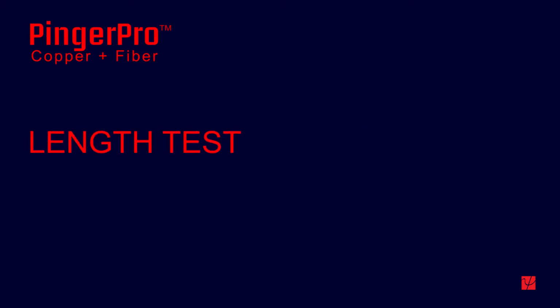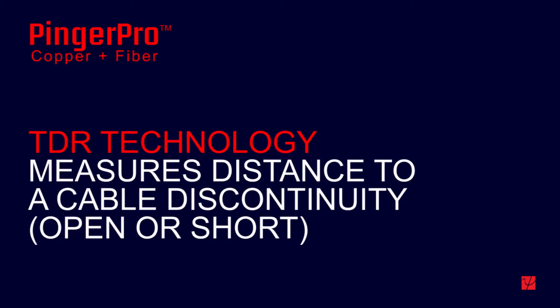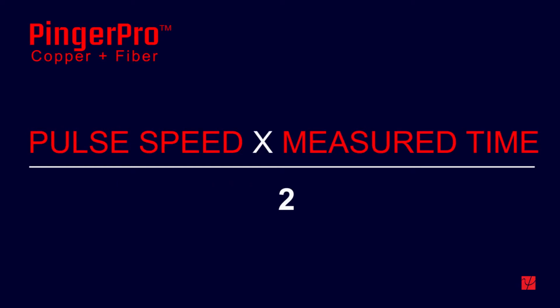The length test uses TDR technology, which stands for Time Domain Reflectometry. A TDR measures distance to a cable discontinuity by sending out an electrical pulse and measuring the time it takes to see the pulse reflection. Distance to the discontinuity is calculated by multiplying the speed of the pulse by the measured time and dividing by 2 because the pulse traveled out and back.